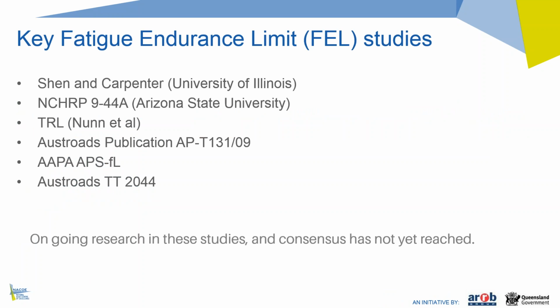To give you a bit more background, currently asphalt thickness continues to increase with increasing traffic, and there are a lot of studies nationally and overseas which suggest that when the asphalt thickness goes to a certain point, continuing to add to it doesn't really bring much benefit.